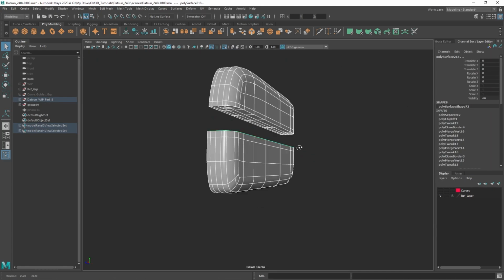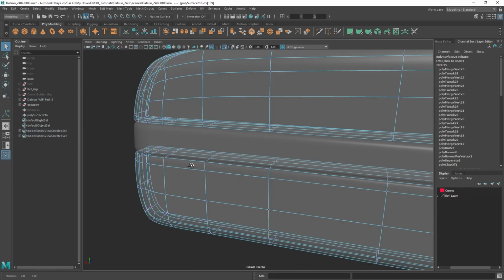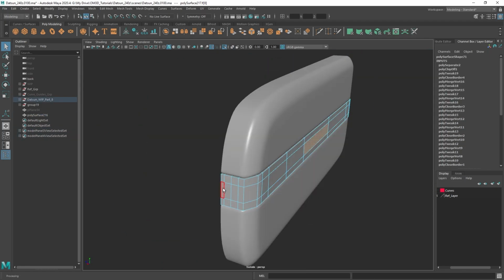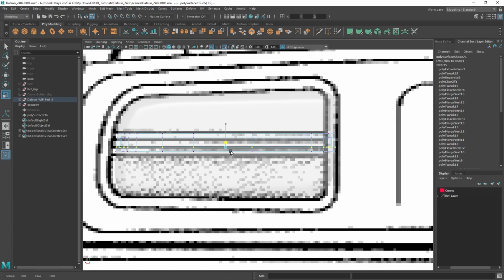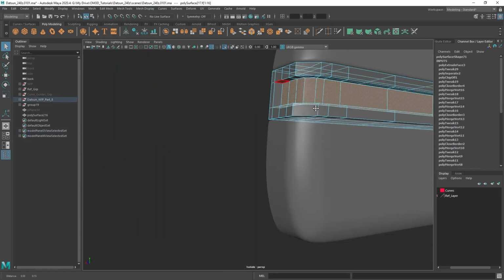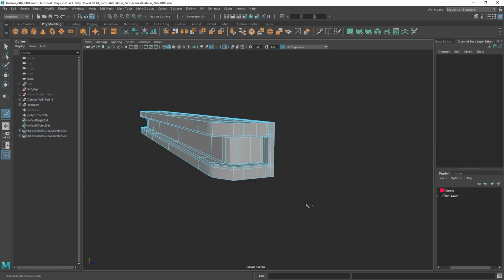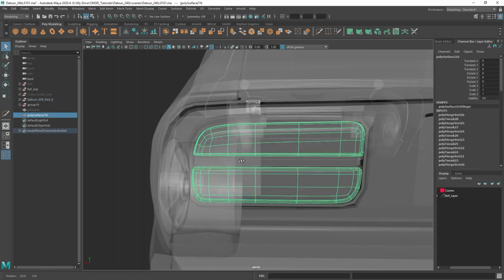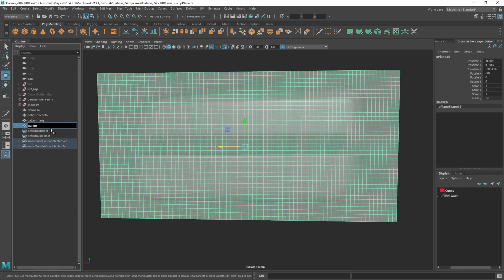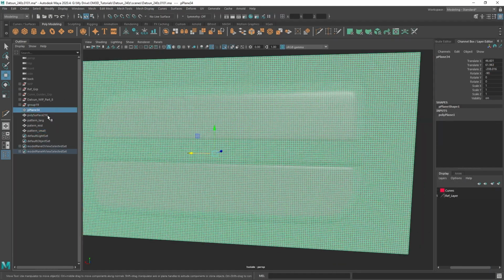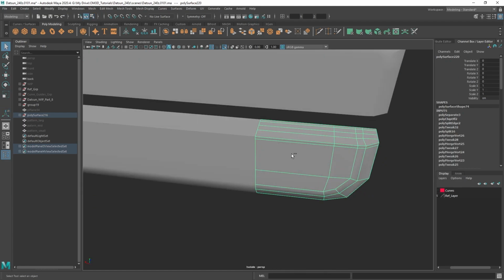I use the modify pivot with D, and then snap the pivots and move the vertices. So I go ahead then and grab the top pieces of that bezel too, and then I add it to those taillight pieces. Now I'm just doing some simple extrusions. I'm moving the edges, just getting the right form. Once I do that, I go back and forth a bit, and I just add in those holding lines. Now I'm finally getting to the point where we just covered right before the time lapse, where I'm creating the 3 different variations. So the small, medium, large patterns. So we're going to have the small, medium squares, or the medium, large squares, and then the tiny patterns.